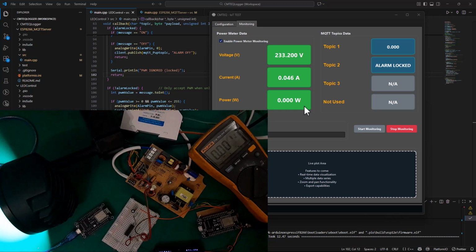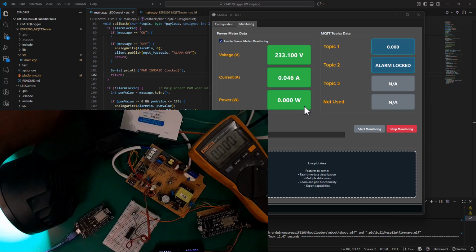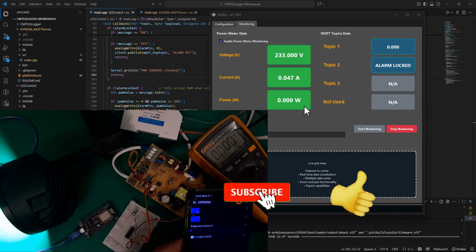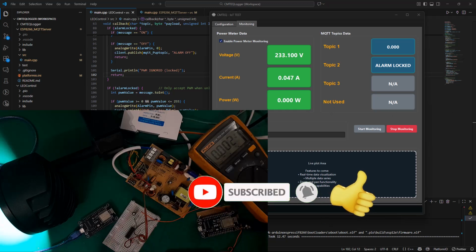So that is it, guys, for these very simple IoT integrations of an LED dimming application. The end goal here is that I want to design a very small PCB that will take the RC filter with an ESP together with a small power supply and build it into the track light here and be able to install it somewhere. That way, the ESP will connect to my broker and I can control using my cell phone the light level wherever the track light will be installed.